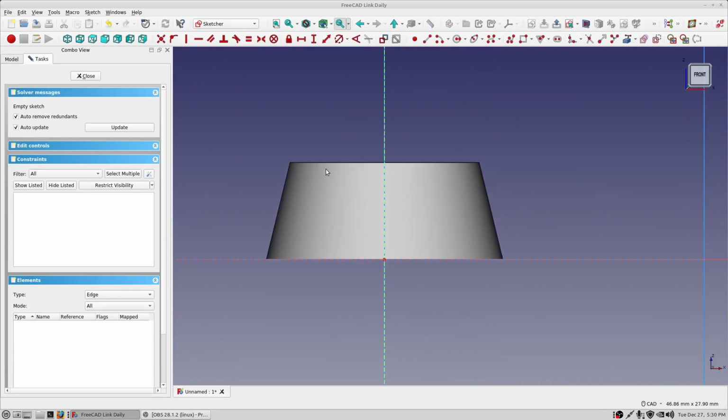So we need some external geometry so we have something to attach this tab to. In order to do that, we go to this external geometry actions, this tool right here, and we mouse over this corner and we get that yellow line. We click on that, it goes red with 2 points, hit escape and cancel the tool. So there's our external geometry. The next thing we want to do is create the wing or the tab that we want to put on this knob.